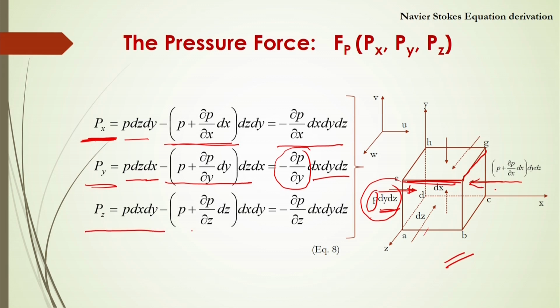Similarly, if you calculate the pressure force in the z direction, then P z will be equal to minus dou P dou z into dx dy dz. So, in this way we can easily calculate the pressure force and its components in the x, y, z directions.